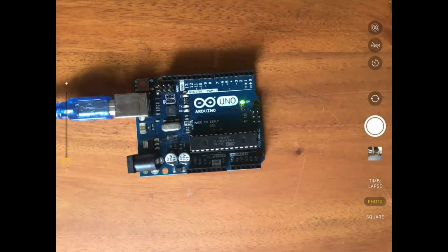For those who have not yet used their Arduino, this would be your first experience with it. So remember the steps. Open a sketch, write a program. In this case, this is a built-in program. Always make sure the COM port selected is the one attached to the Arduino. Then, very important, compile first, check for errors, and then upload. The compiling part is in the sketch, and there's an arrow there that says upload as well.